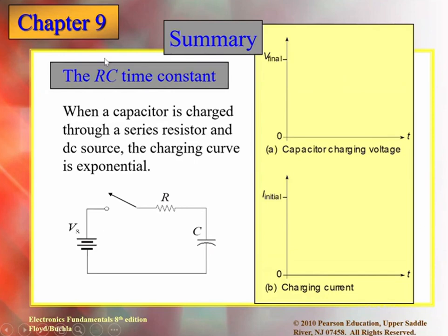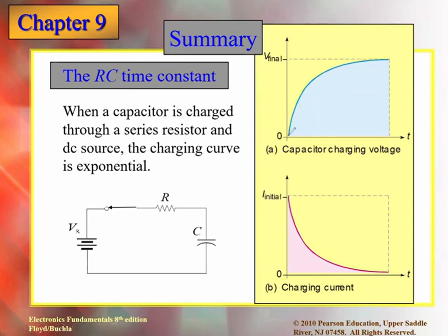And I told you, you can consider a capacitor as an empty glass, correct? As long as it is empty, it keeps filling and allowing the current to flow through it. Once it is full, it creates a wall barrier, so it will not allow current to flow. You will see what happens as I close the switch. Look, as I close the switch, the upper one is the voltage developed across the capacitor. Initially the voltage across the capacitor is 0, and as I close it, it allows the current flow. As the current flows here, the voltage across it starts building exponentially. See this one.